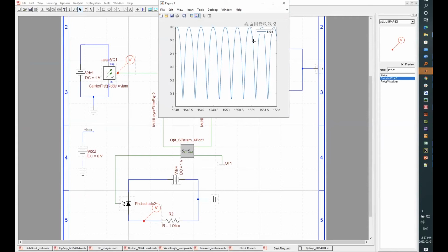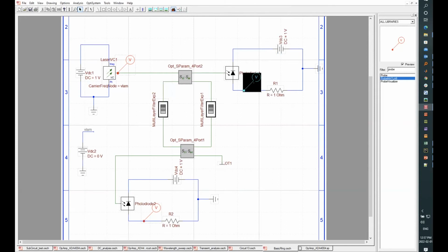And like I said, there is also a way to set up your MATLAB code or any script for doing the post processing as well. What you have to do is define the path for that particular MATLAB code in the JavaScript. And once you double click your probe here, it will open the results in MATLAB, as well as it will run your script, and it will give you the results of your post processing as well. So this is just a demonstration to show that we have hooked up the OptiSPICE engine to MATLAB as well.